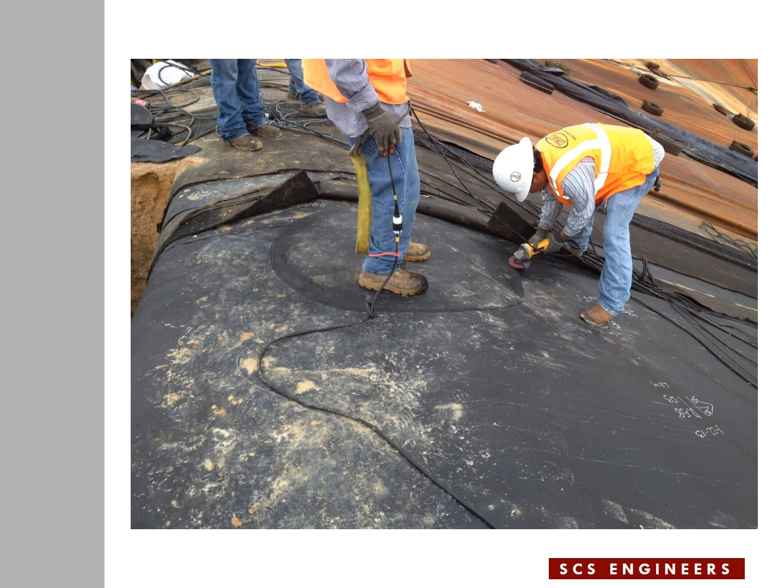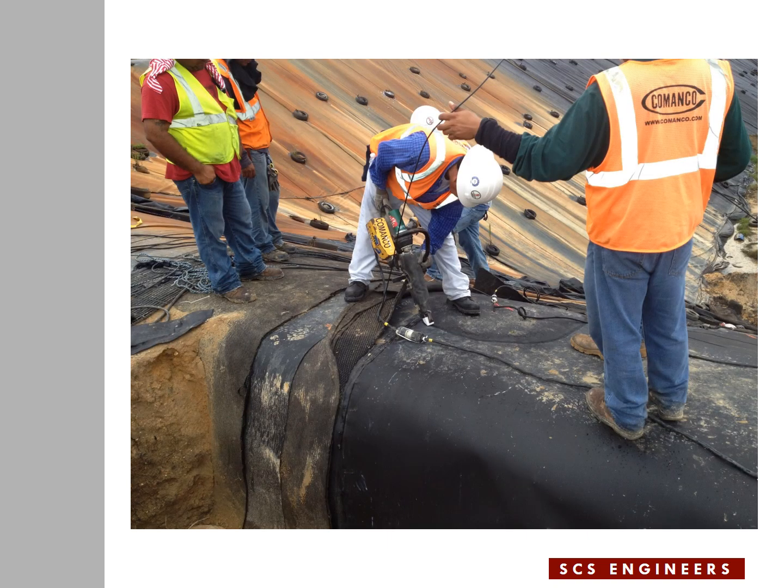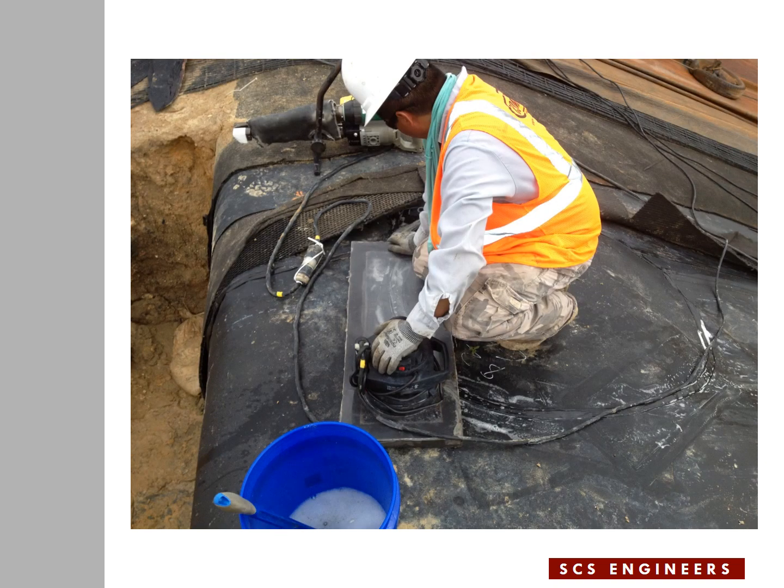Repairs are done, patches are installed, grinding of the extrusion weld area takes place first, and then extrusion welding takes place. Basically, these are the few steps that we go through in order to complete the geomembrane work, and then the vacuum testing takes place on extrusion welds.